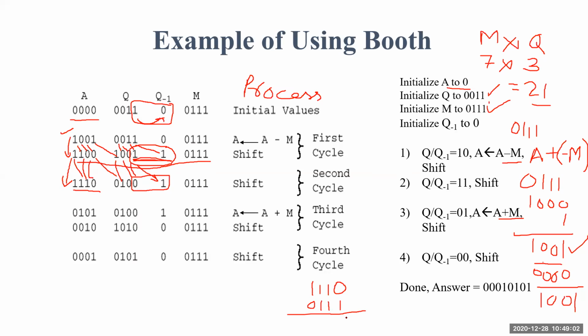So see now, if I add, 1 and 1 will be 0 and 1 carry. When it is three 1s, it will be 1 and 1 carry goes over here, and it's 1 1 over here, 0 and 1 will be carry, and this can be discarded. If you discard this particular carry, your sum will be 0101. So this is your new accumulator value, which is obtained after doing the A plus M operation. So you got 0101, and that's why we have stored it here.